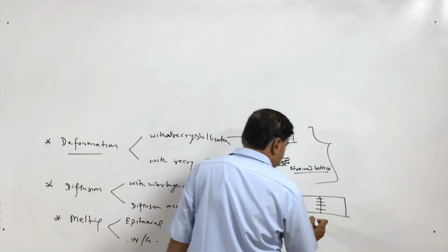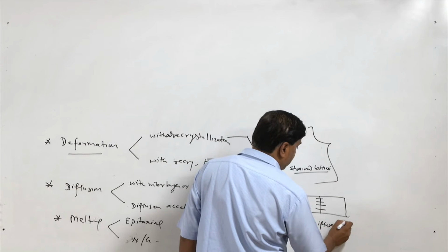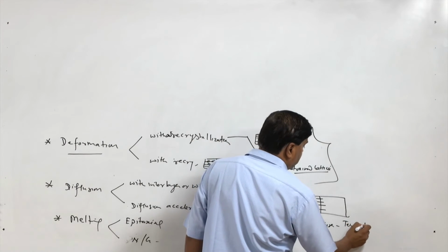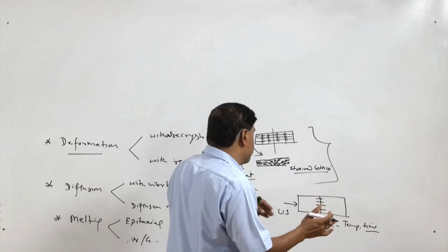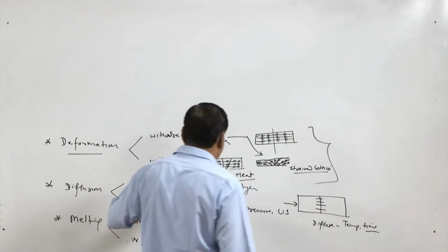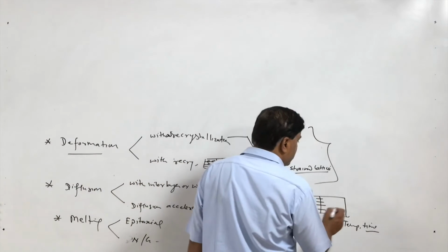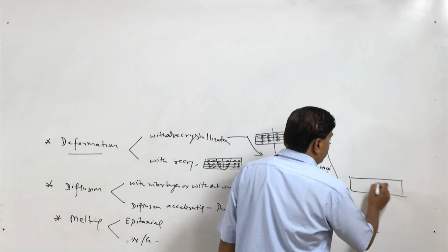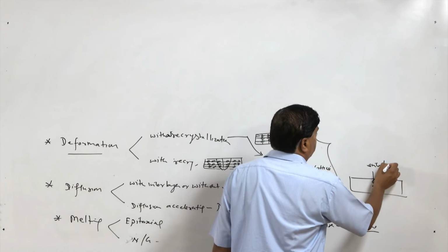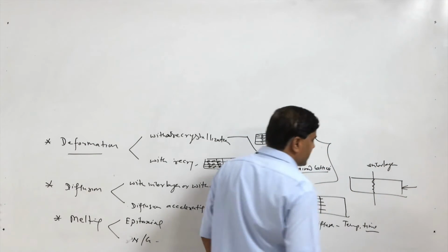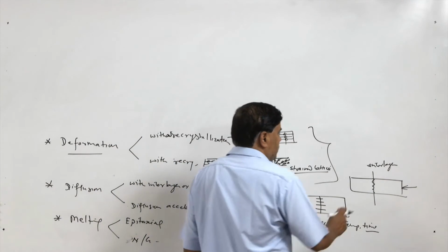So, the diffusion is facilitated basically by temperature over a sufficient period of time. When sufficient time and temperature are given, the bond at the interface is formed. To facilitate the diffusion across the interface, sometimes, to overcome problems related to surface roughness, interlayers of soft metals are used. Under pressure they get deformed and fill the cavities and irregularities present at the surface.